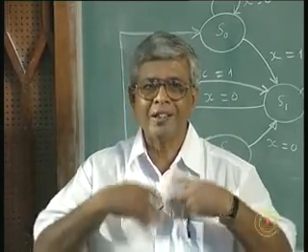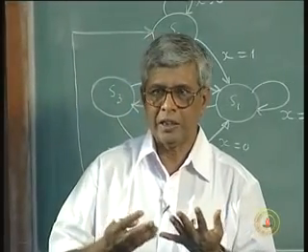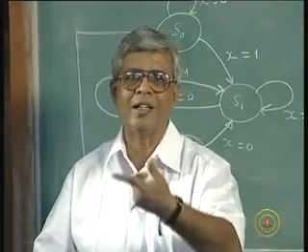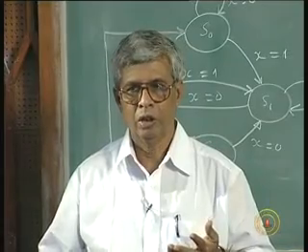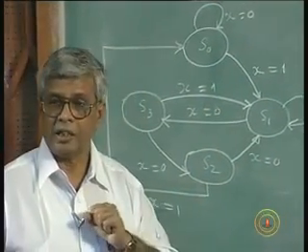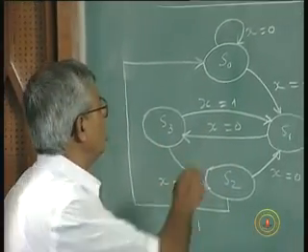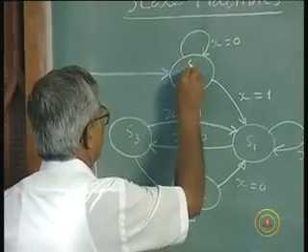Is there an output other than the state? No, the state output is the same as the output. If the circuit is in state 1000, I can say the count is 8. On the other hand, this circuit can have an external output in addition to the state it is in. In S0, Z can be 0.